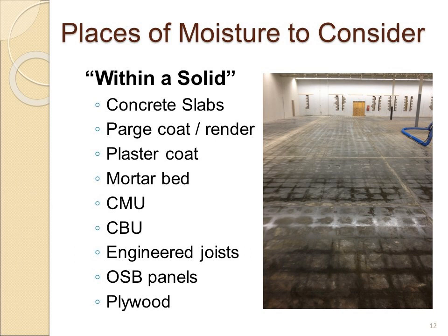As in the case of this picture here, when we think about a place of moisture after a VCT is removed, and you look at the floor, you can actually see the residual moisture coming to the surface and condensing on the surface of the concrete. But it's not always so obvious where we could see that moisture, but we know it's there.